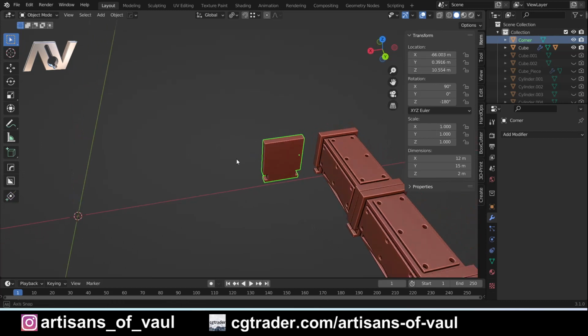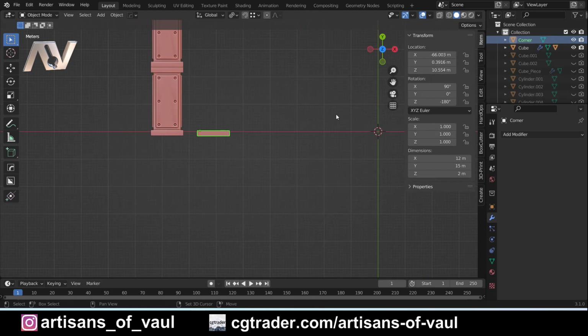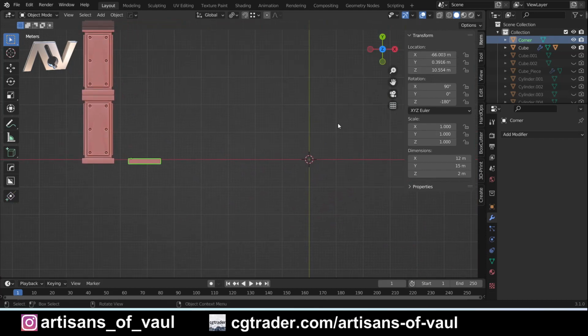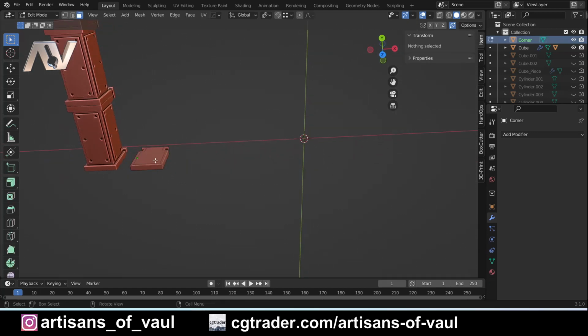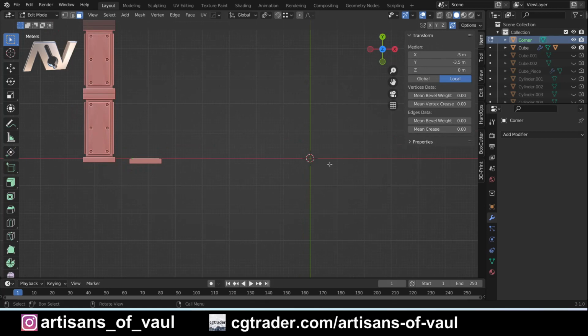Now obviously I moved this out the way earlier, but importantly, if I just go to the Z axis on the gimbal to look down, I can really quickly put in exactly the information that I want. So the first thing is on the Y axis, that's the green axis, I need my object to be at 0. So I'm going to put 0 there. So now the face that we're interested in, that face there, is in line with the cursor.